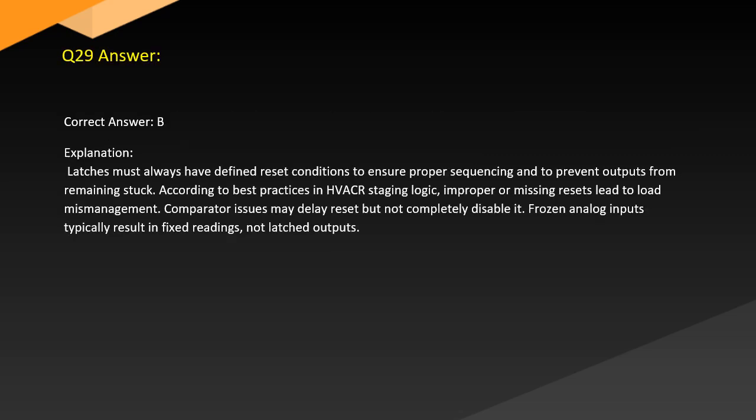Answer. Correct answer: B. Explanation. Latches must always have defined reset conditions to ensure proper sequencing and to prevent outputs from remaining stuck. According to best practices in HVACR staging logic, improper or missing resets lead to load mismanagement. Comparator issues may delay reset but not completely disable it. Frozen analog inputs typically result in fixed readings, not latched outputs.